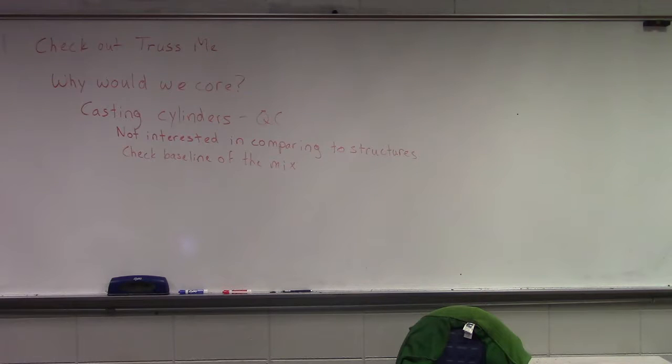And then what the ASTM practice says is those cylinders can stay in the field for 24 to 48 hours. At that point, you've got to get them back to the lab. We need to minimize the amount of temperature fluctuation that they're experiencing. Further, we need to limit the range of temperatures out in the field. We need to have a cooler, and some sort of heating facility for them in the wintertime, so that they aren't having the same temperature fluctuations exerted on them.